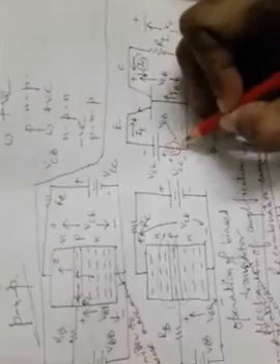So we can say that if this Vin is increased at the input circuit of this transistor, the upper side of VO will be more positive than the lower side of VO, because IC will be decreased in that case, because of the overall forward bias being decreased at the input side. Because of IC being decreased, the lower terminal of RL will be less positive than the upper terminal. So we can say that as Vin goes on increasing, VO goes on increasing.